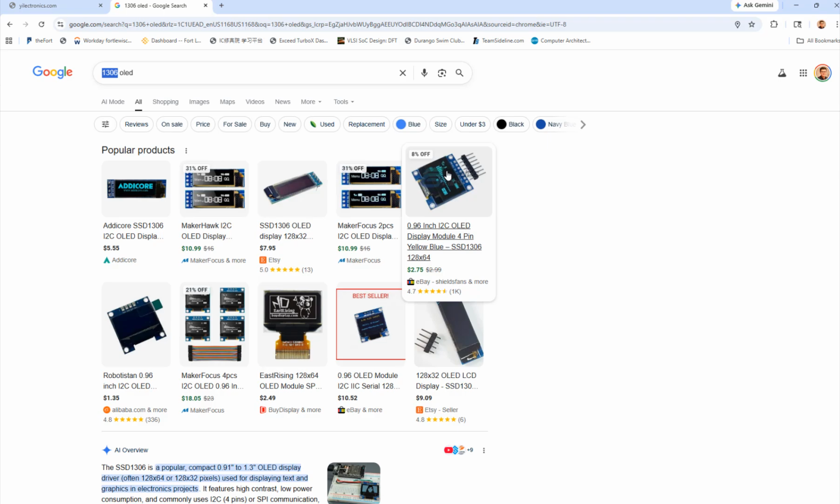The signal definitely needs to be amplified because the light penetrates the skin on your fingertip, and the oxygen in your blood can absorb the light, but the rest will go back to the sensor. So eventually, depending on how much blood you have in the fingertip, because whenever your heart beats, it pumps blood to your fingertip, you get more blood at the fingertip, and also more oxygen there as well. So the oxygen molecules will absorb the IR light. So if you have more blood at the fingertip, you will have less reflected IR.